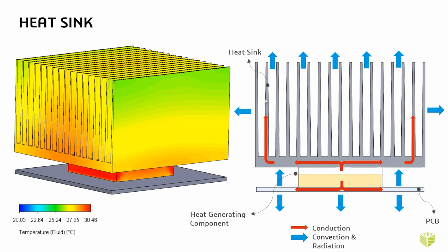The fins have a lot of surface area to remove thermal energy through convection. Radiation can come into play here if the temperature difference is very significant, but in a closed system and the temperatures that I'm talking about, largely I can ignore radiation.